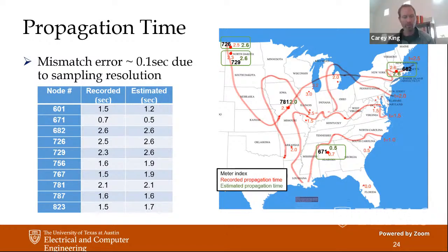Okay, thank you. There's one question here, just on the Florida blackout that you showed. I think you said it was a generator that went off that caused the blackout, do you know how much that was in relation? So usually an event like that has to be on the order of hundreds of megawatts. It's probably hundreds of megawatts. I don't have the exact number, but maybe even 1,000 megawatts, I would say. For ERCOT, our peak loading is 72 gigawatts, so losing 1% may be a very big number.